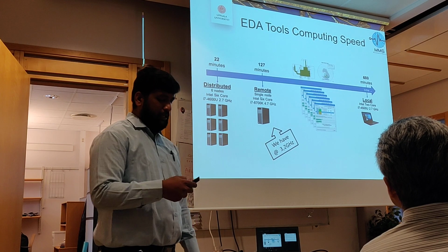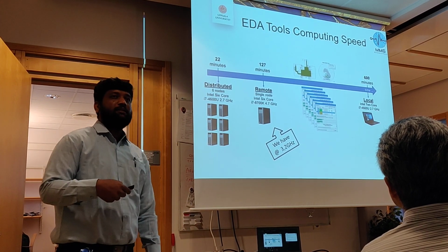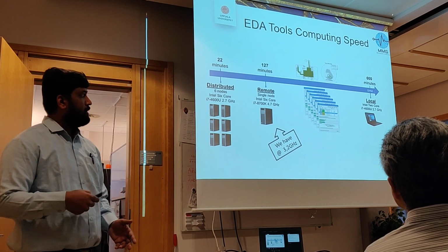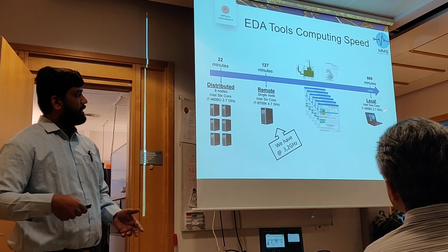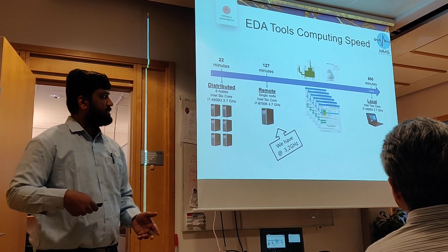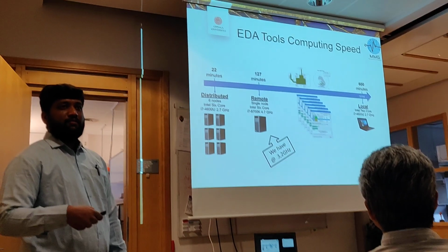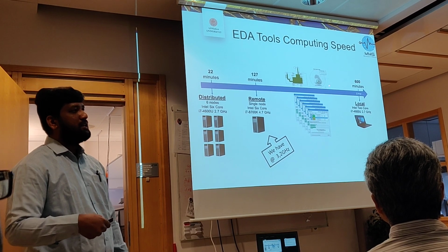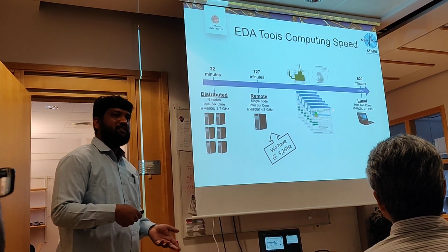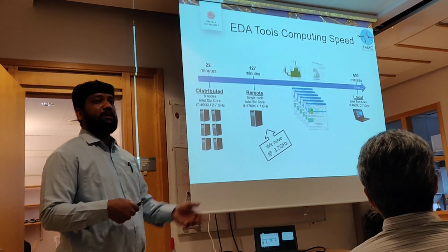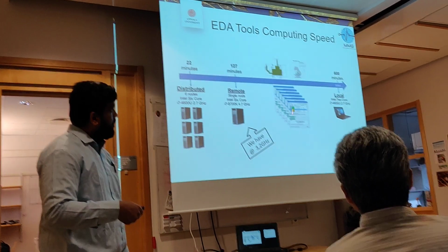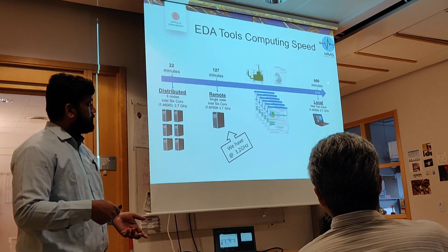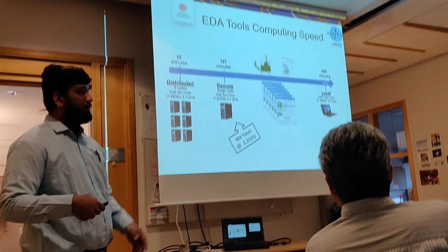And most of the designers working with EDA tools will complain that the software is slow and not working well. I would like to say that if they are using a dual core i7, it will take a lot of time if you are doing EM structure simulation, because in the background a lot of netlists will be created, and every time it has to consider the data file. A lot of complex calculations will be happening in the background, so it will take around 600 minutes if you have a dual core.